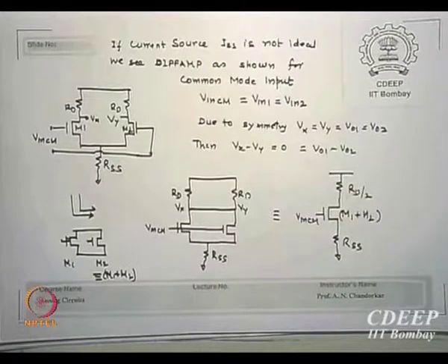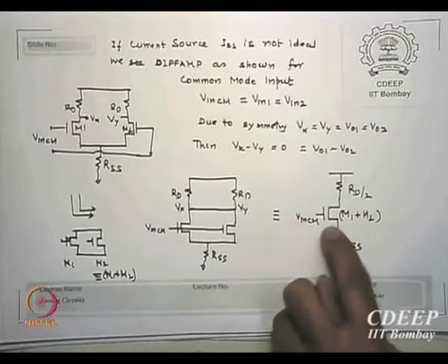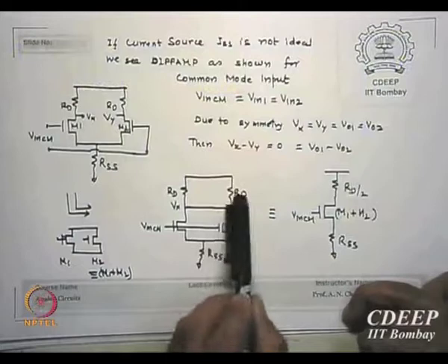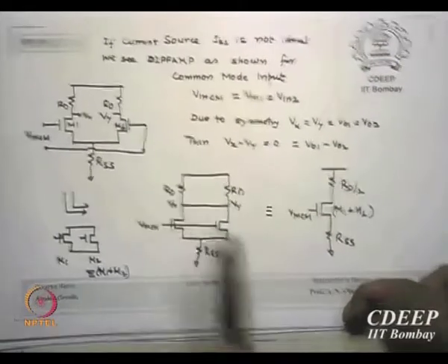So for M1 and M2, assuming VTs are the same, everything else the same, betas the same, it is only twice the width. So the transistor has twice the width. Is that clear? This is called an equivalent transistor. Two transistors in parallel, their widths sum. So this circuit then reduces to, can you also see these RDs are also parallel?